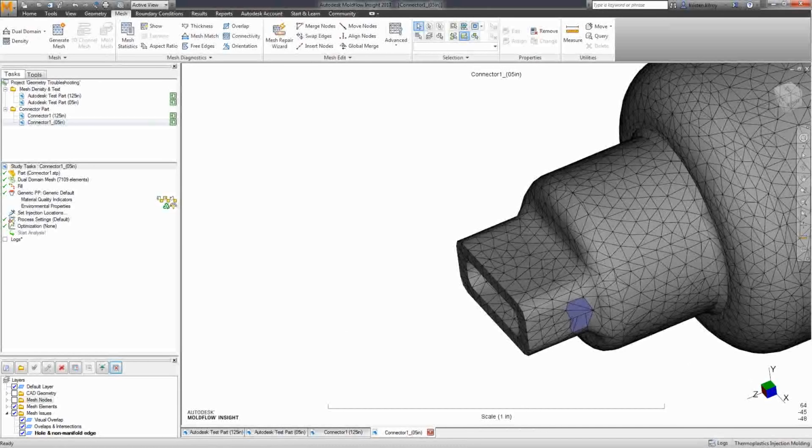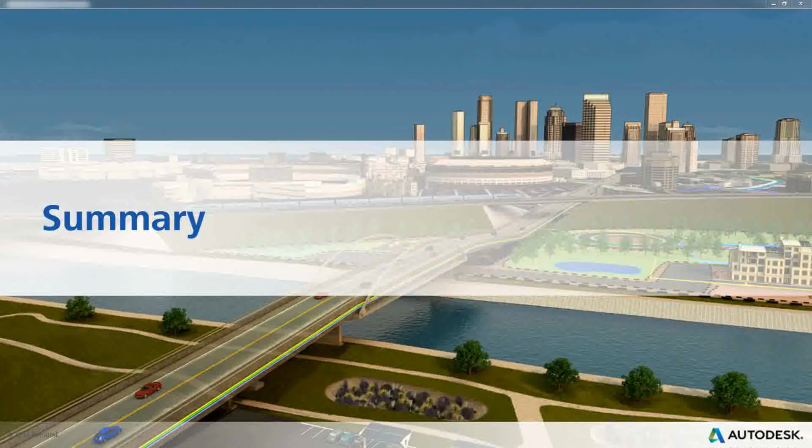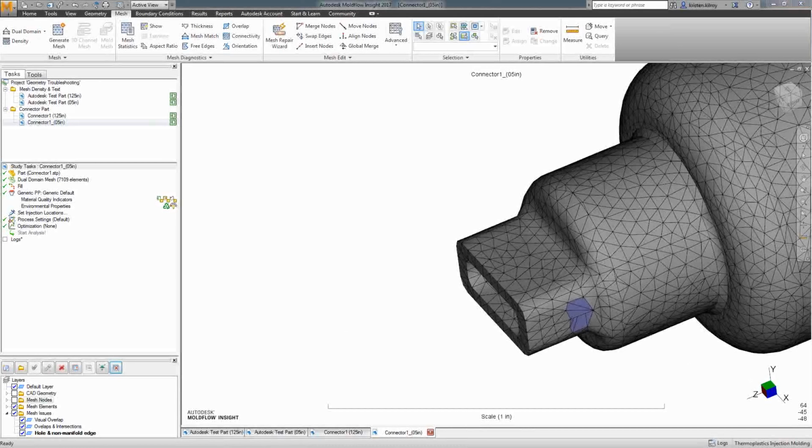Basically, this one is: for a dual domain mesh, if the addition of chord angle length, for example 45 degrees, 65 degrees, etc., does not result in improved reciprocal match ratio, is there any advantage to using the chord angle in meshing beyond making the part look nicer?